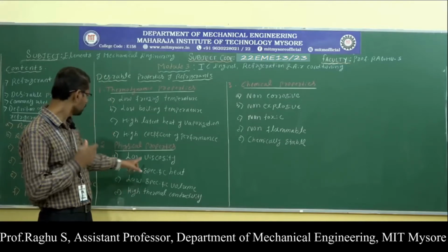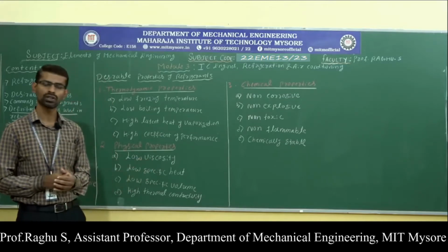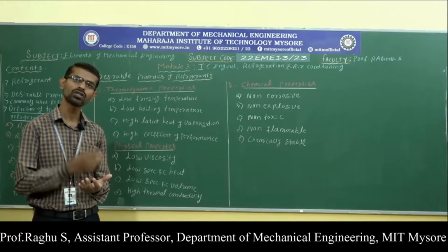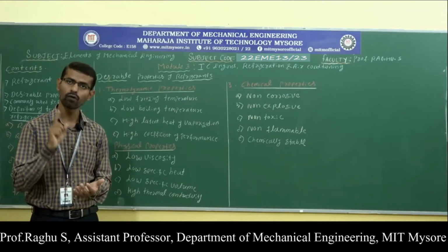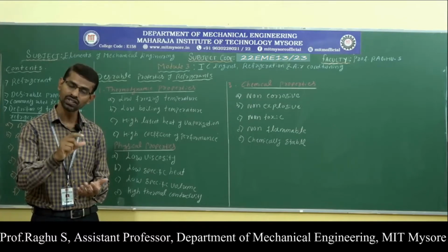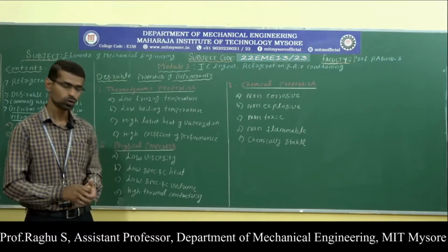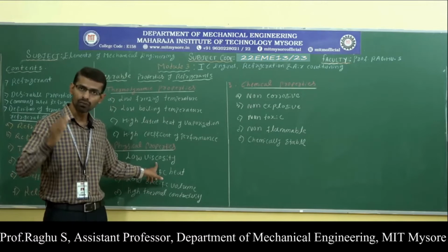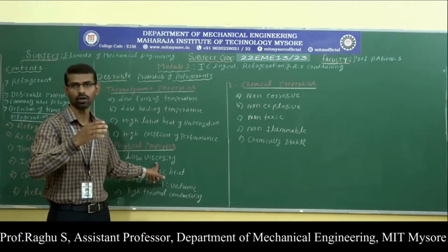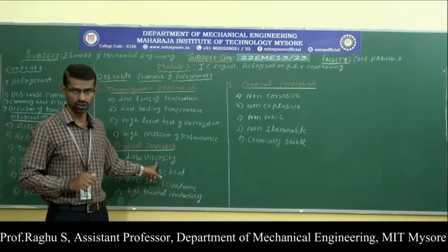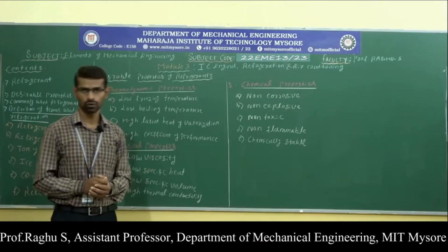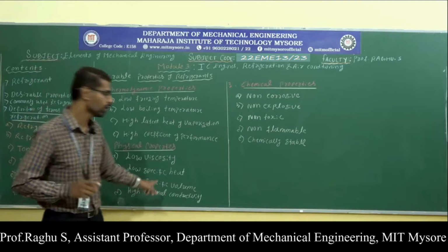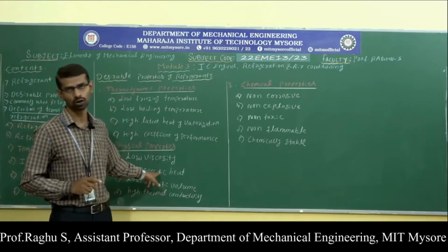The next one, physical properties, like low viscosity. What do you mean by viscosity? Viscosity is nothing but resistance to flow. A good refrigerant should have low viscosity in both liquid state and gaseous state, so that we can easily circulate the refrigerant throughout the system with less pumping pressure. A good refrigerant should have low specific heat also.